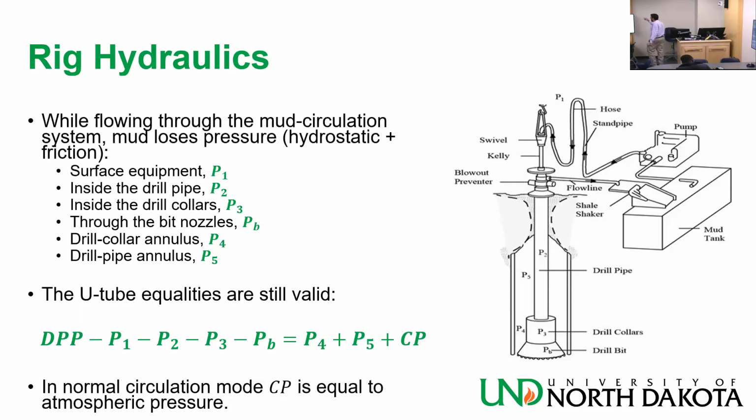But then when you go downhole and you start going deeper and deeper, you have more and more weight above you, right? So we add pressure because you have more weight above you. And this is what you learn with that 0.052 number. It's the hydrostatic weight. And then you lose height, and you come back to the surface. So whatever depth you are going to gain, and increase the pressure, you're going to lose it when you come back up, right?